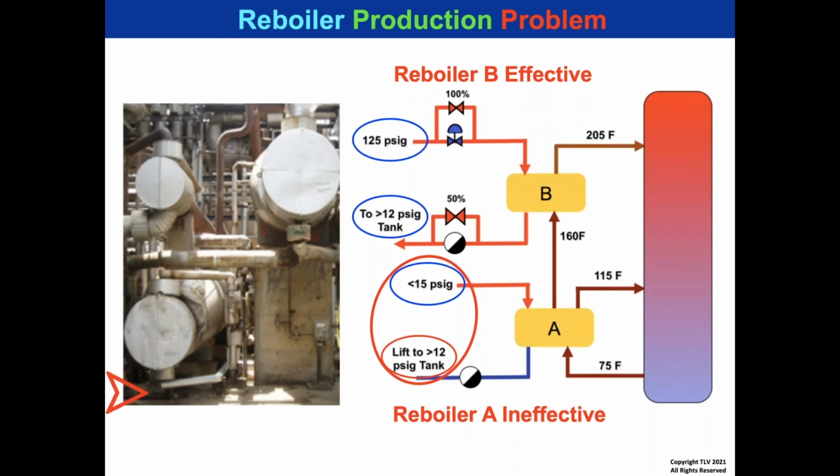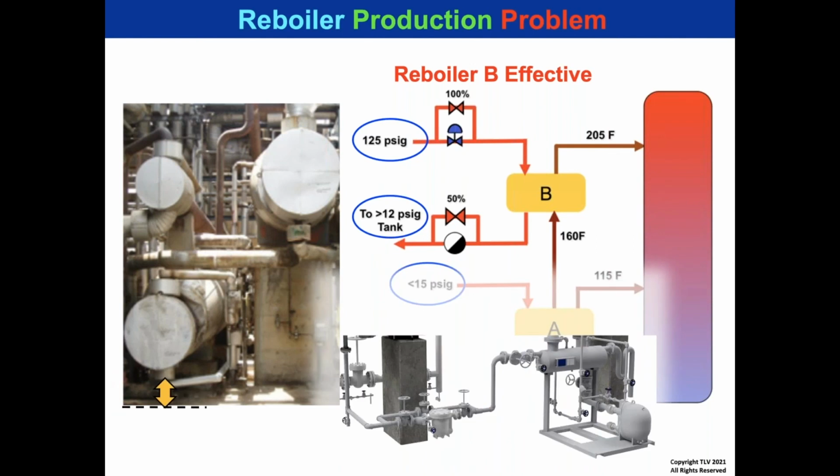So in this case, the outlet of the reboiler was so low that we couldn't get a pump trap in there, but you could make a recommendation to come out of it with a steam trap and discharge that into the pump only, bring in the secondary pressure here to pump it out, and that gives them the best of both worlds. They put a pump in there, they get to use the low pressure vent steam, so that improves their steam balance and they're not venting so much, and they get the operation of reboiler A. Everything is working well then.